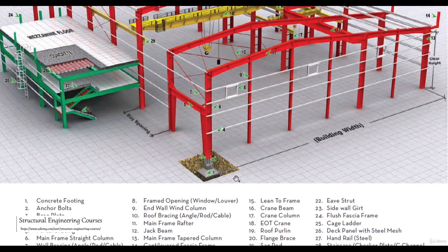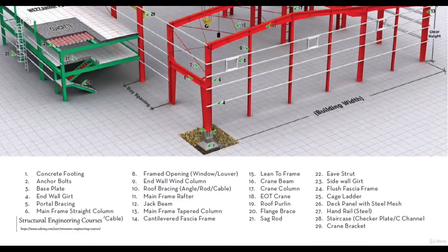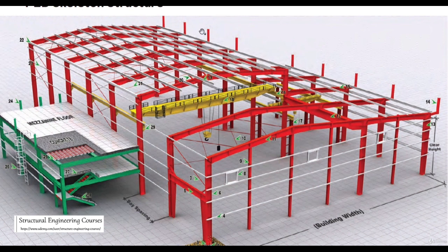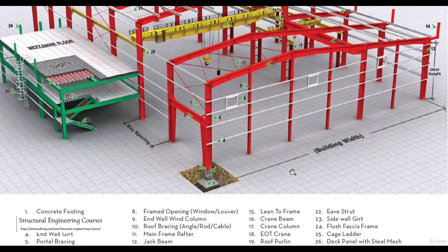Number 13 is the main frame tapered column. So this is also called a main frame tapered column. Number 14 is a cantilevered fascia frame. So here you will see from this point to this point they have made this cantilever fascia frame, which might be used for holding any banner or any signboard arrangement here. And 15th is the lean-to frame.